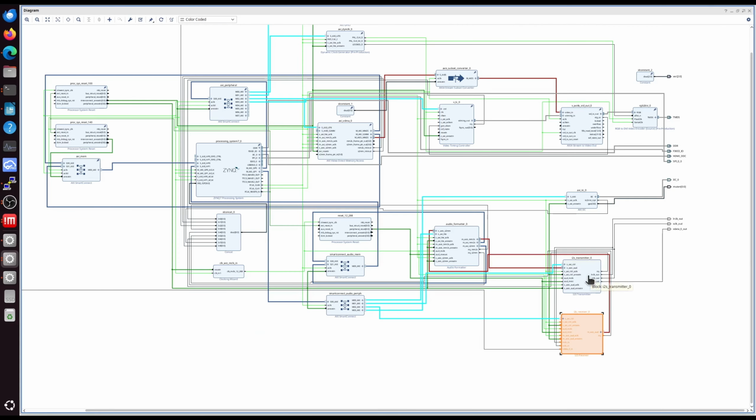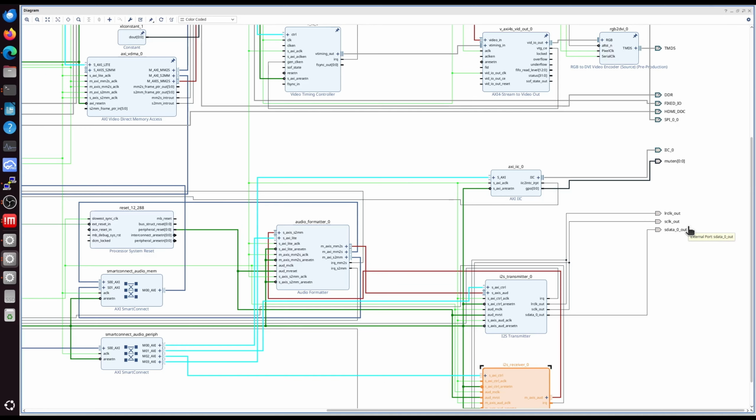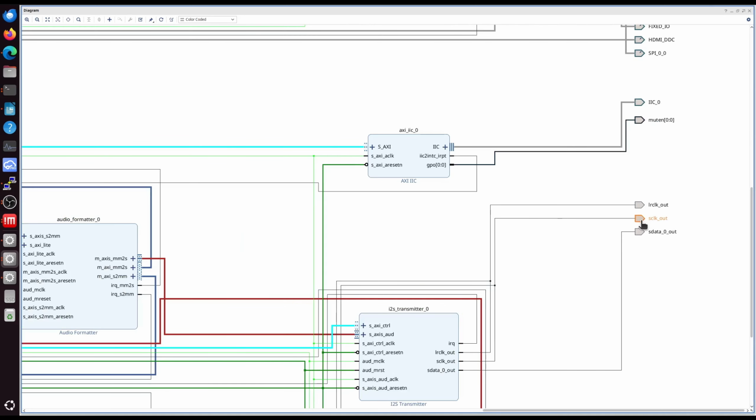And then coming out of the transmitter is going to be a few things. So I've got my actual I2S clock or S clock, also called the bit clock. I then have the LR clock, so that's a slower clock that's pretty much matching up with the sample rate, and I'm targeting a 48 kilohertz sample rate. So 48 kilohertz for that, and then the S clock out, I believe, is roughly 1.5 megahertz, and I'll pull that up on the scope so you can see that. And it is dialed into what the spec says I should be running for those.